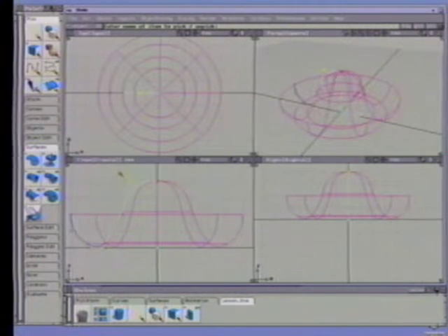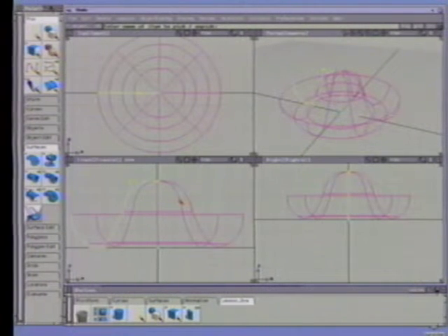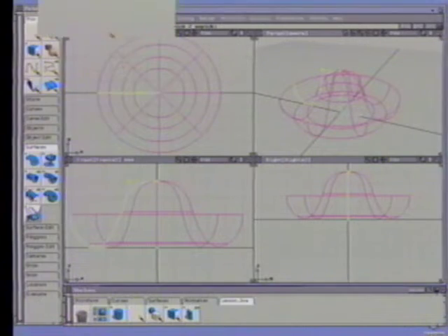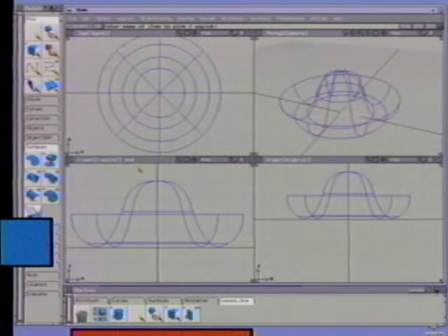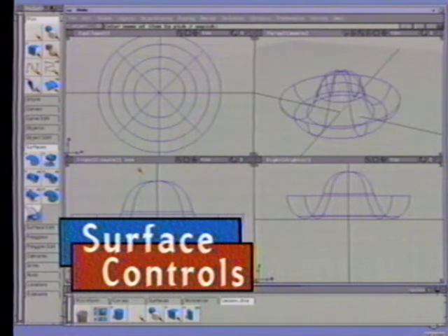Select Pick Object. Click-drag a pick box around both the sombrero and the construction curve. Next, press the Shift key and click on the surface of the sombrero away from the curve. This unpicks the surface while leaving the curve picked. Select Delete Active. At the prompt, click on the Yes button to break construction history and delete the curve.